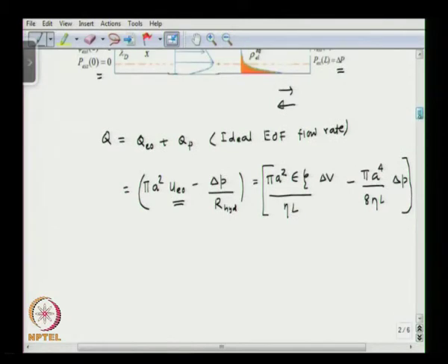So from here we can find out the pressure flow characteristics of the electroosmotic pump, what is called PQ characteristics. If you say zero flow, what is the maximum pressure that we are going to expect from the pump, and for zero back pressure what is the maximum flow rate that we will be expecting from a pump. Pumps are characterized by their pressure and flow characteristics. So let us look at here.